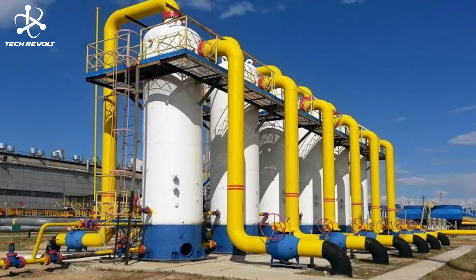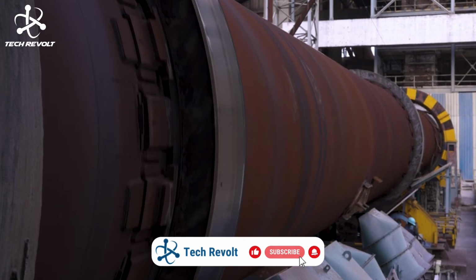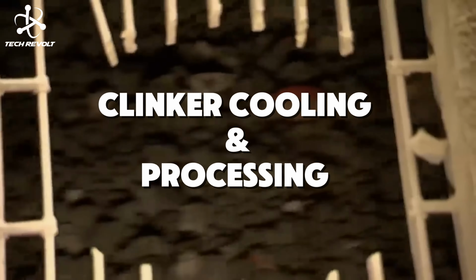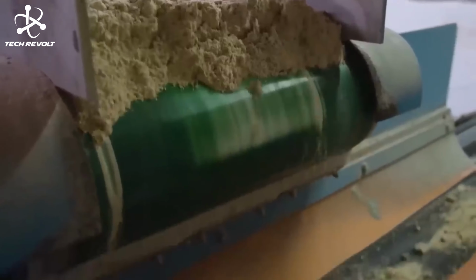Some form of heat exchanger is commonly incorporated at the back end of the kiln to increase heat transfer to the incoming raw materials and reduce heat loss in the waste gases. Clinker, cooling and processing. After formation, the hot clinker needs to be cooled quickly and efficiently. It passes through a clinker cooler where air is blown through it to reduce its temperature.